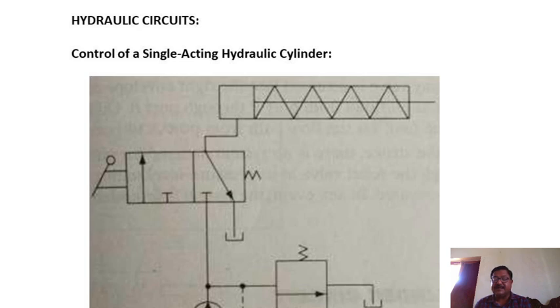Cylinder synchronizing. Cylinder synchronizing means cylinders should operate sequentially so that the pressure is applied differentially. If a large quantity of pressure is coming from the pump, that pressure is differentially bifurcated into the different circuits so that the whole pressure is utilized properly.